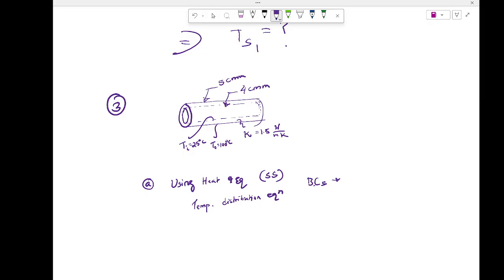Once we have the heat equation simplified, K is constant, that is important. But think about the surface temperature inside and outside. Are those changing? No. So those are your boundary conditions. Everybody understand that? It's just the same problem that we did in last class. Very similar, but it's a cylindrical coordinate system problem.